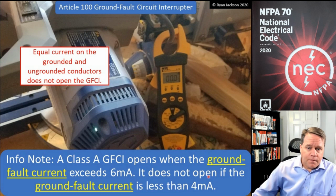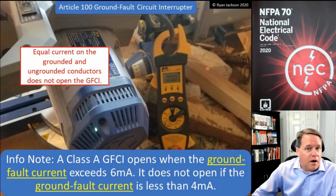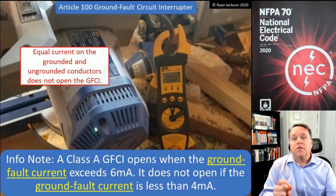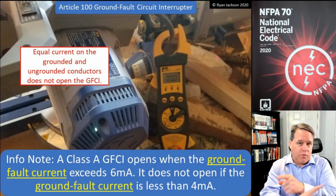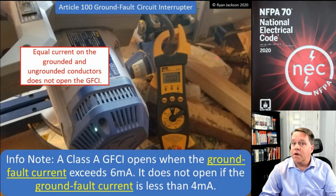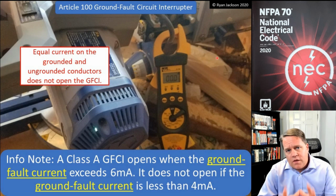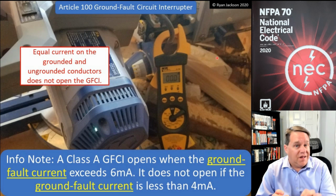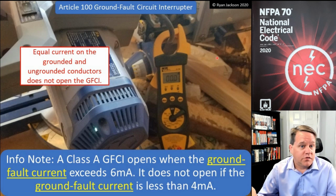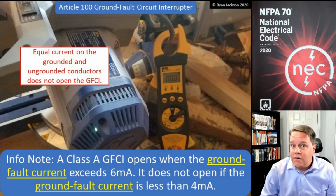So here on my saw, I've pulled the trigger and I'm measuring the current around the entire cord. Now, if I have current, we have to go back to Kirchhoff's law. Current leaving the power source must equal current returning to the power source. If 10 amps leaves the source, 10 amps has to return to the source. That's not my opinion. That is a fact. So we want the current to return to the source on the intended path. If it goes out on the hot, we want it to come back on the neutral. Or if it's a 240 volt circuit or a 208 volt single phase circuit, if it goes out on phase A, we want it to come back on phase B.